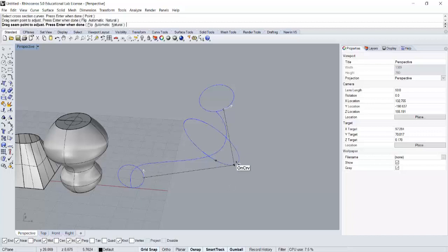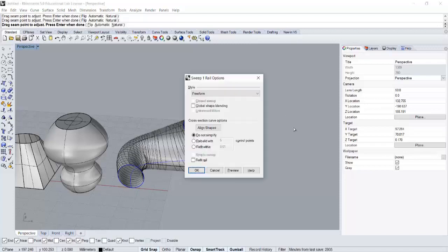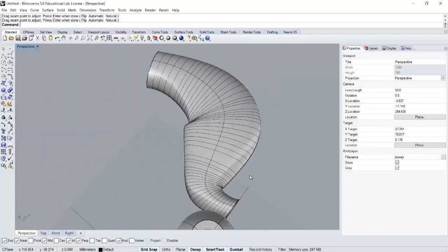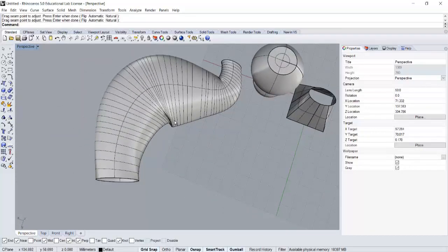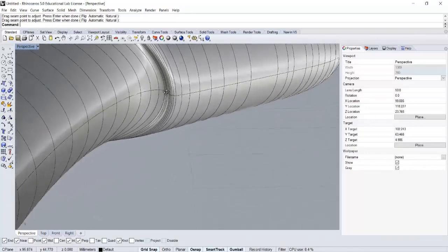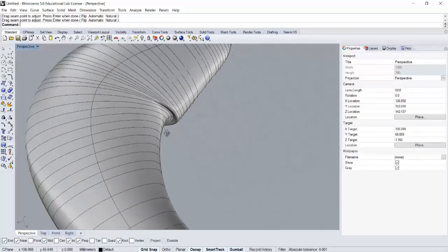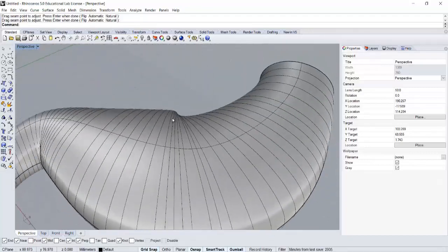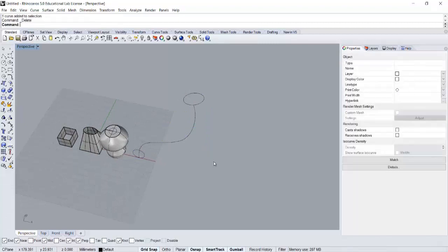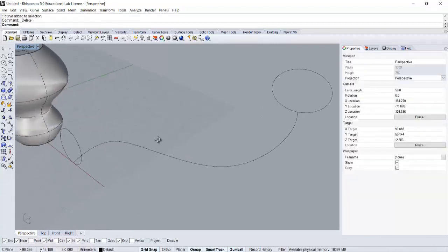So let's make sure that those all tie in with each other. So I'm on that side, and that side. So you can see, because I went quite wide here, it's starting to struggle and it's got self-intersecting geometry a little bit in there. I might have just about got away with that, but that's not the best. However, you get the idea. I'm going to get rid of those for now.